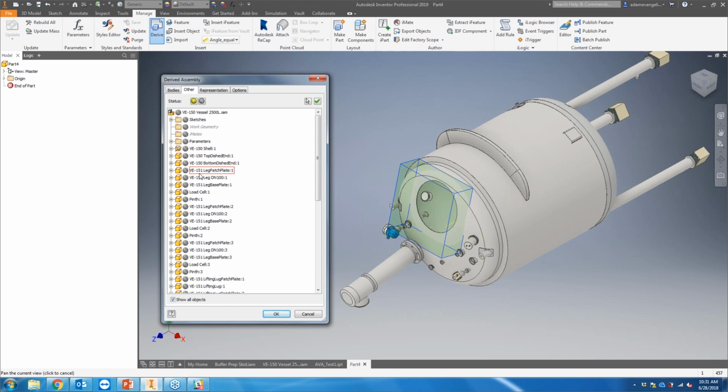And this is going to be the biggest distinction from the Shrinkwrap command here. You're going to see a really similar feature tree over here, but instead of the individual parts, you're going to actually see sketches, work geometry, iMates, and parameters, right? So this is essentially all the sketching, work geometries and reference geometries that are associated with these individual parts. So if I want to bring over a really useful sketch or construction line that I made in this particular part, then I could bring it over if I want.